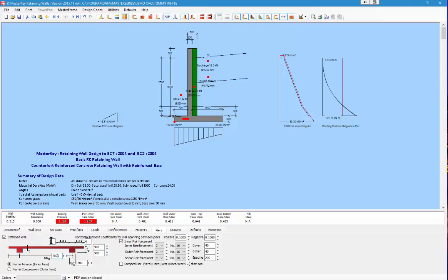And these values are only applicable if we're into masonry. We have the effective outstands that we're allowed to consider. And we can say whether the pier is in compression or tension, which means we can move it to either face of the wall. So pier in compression, then this is all my tension steel. I design it accordingly, or in this case pier in tension. And you'll see that it's giving us some relief in our wall, but not necessarily enough in this example with those additional loading I put on to the structure.